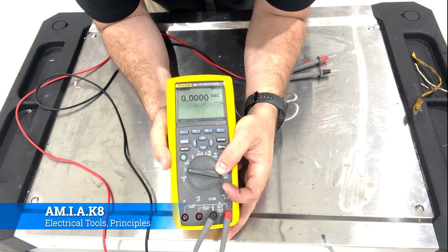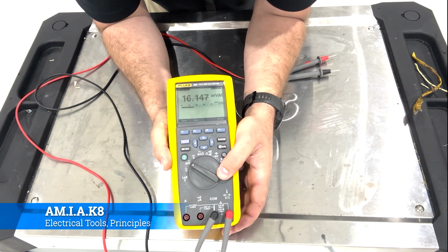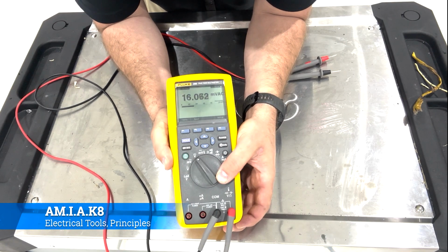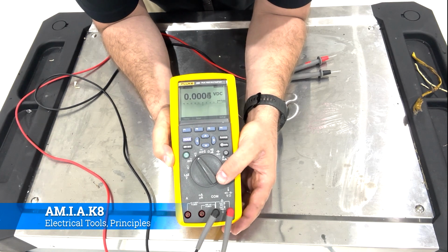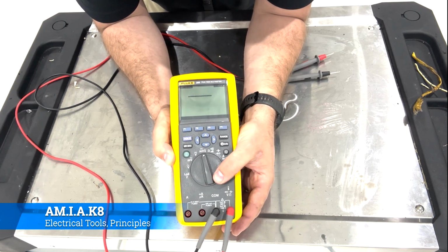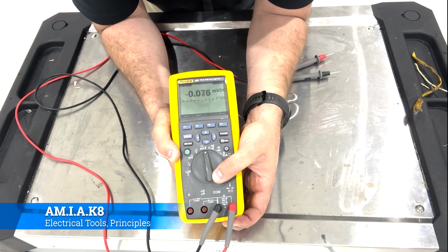It's just volts AC, but you'll see that the range is set so that it goes out to the 4th decimal place on this one. You can go to the next setting where it's millivolts. The next one is our first DC voltage. DC is always annotated by a solid line over a dash line, whereas AC is always a wave.